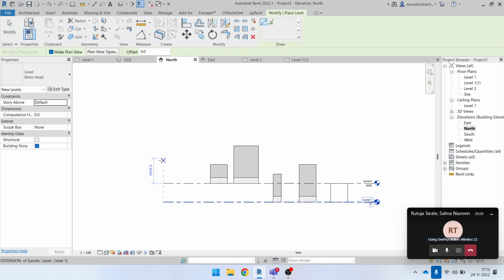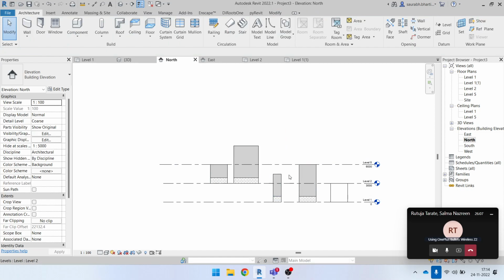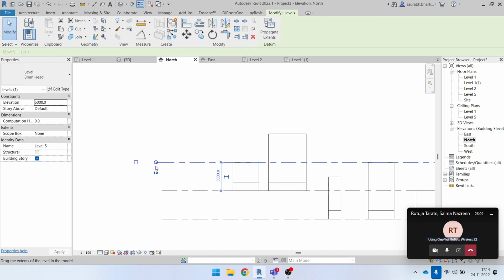Yeah, and in datum you will find Datum level, shortcut is LL. You don't have to go to that place every time. You just press double L on your keyboard, and you will get this level button. Then you have this line, or another thing we have is this pick line. You can always press escape to get out of any part of Revit.